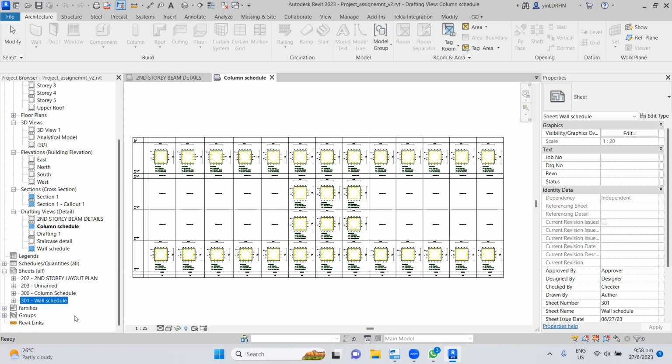So we have some time. Now I'll explain how to put the schedule in Revit. This one you should not confuse. The Tekla structure schedule is a rebar schedule, but the Revit schedule is a quantity schedule. If you want to extract some quantity, then you can use Revit to do it. Basically it's for your quantity takeoff for your cost estimation.